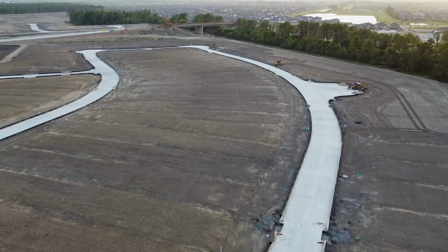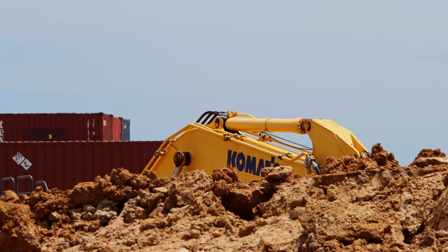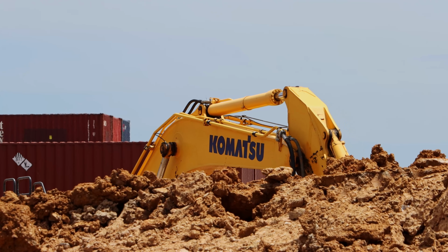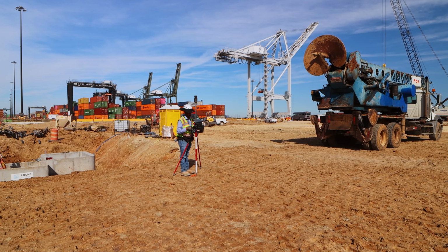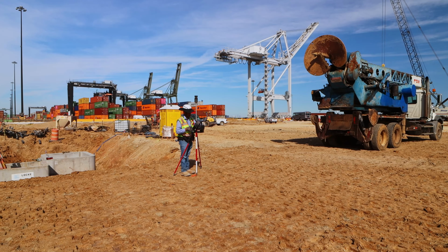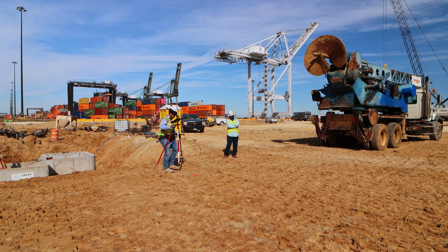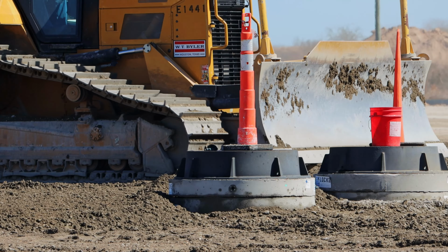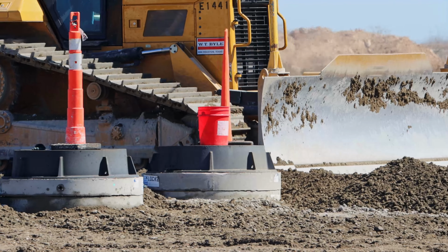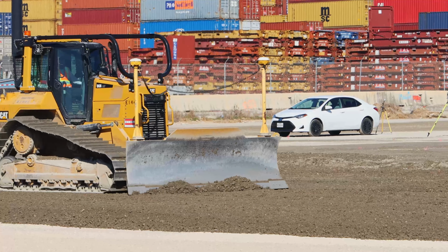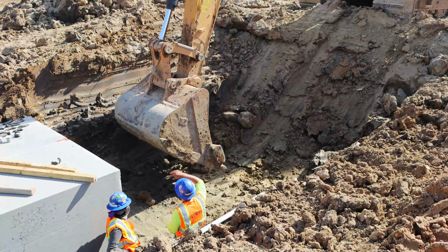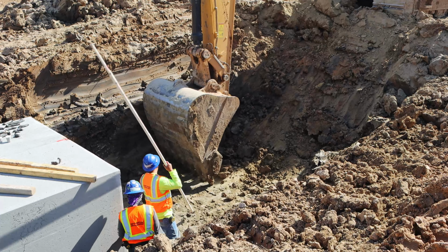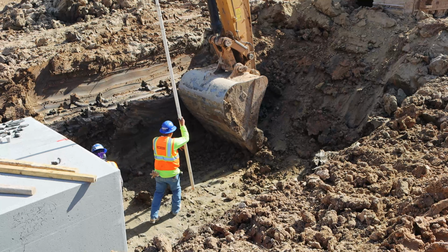There are two activities that engineers need to do in the field: pre-design site survey and geotechnical investigation. The survey team needs to walk the future construction site and record everything in detail. All surface and visible underground objects are recorded, such as manhole lids or outfall pipes. Topography over the entire area is recorded, and pictures are taken. Surveyors are the eyes of the engineers.